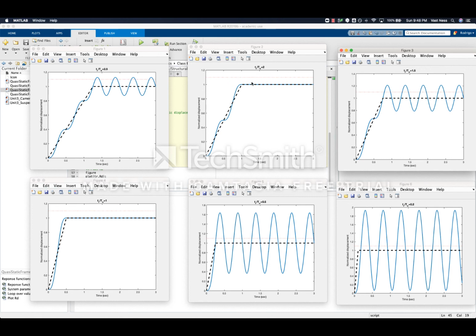When the rise time is exactly 2, the oscillations actually at the peak go straight to 0. And this is actually because the force levels out exactly at the peak of that oscillation, meaning that the velocity at that point was exactly 0.